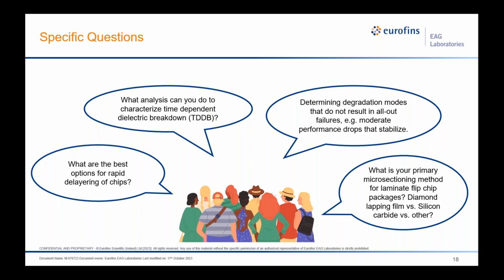If it is deeply functional in nature and doesn't need some crazy environmental variable like radiation, maybe we can utilize other techniques like the laser voltage probe. Maybe a FIB circuit edit will put down pads so that we can access internal nodes within the device, and then during operation, we can see how things are toggling inside. Is the clock actually toggling at the correct frequency? Does it dip out sometimes? Is there an anomaly that happens every 23 microseconds?